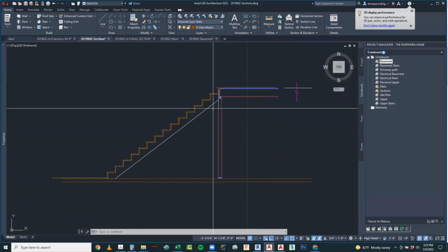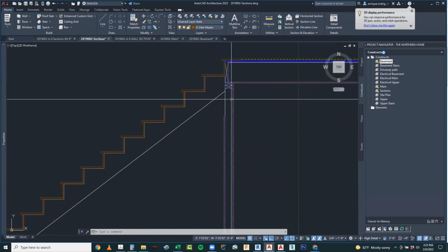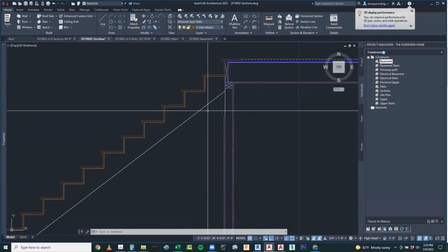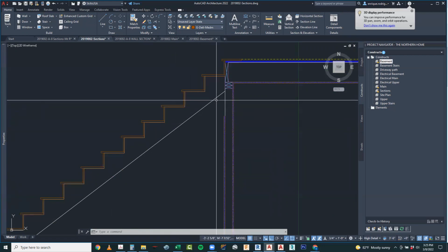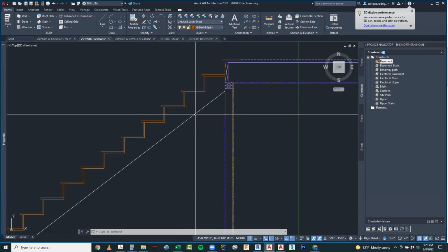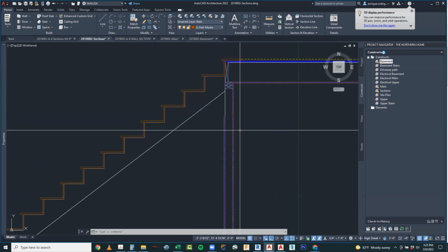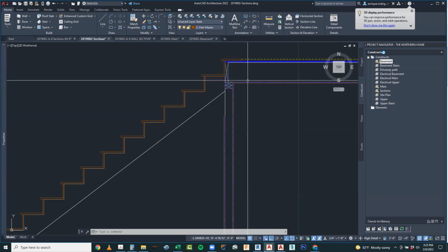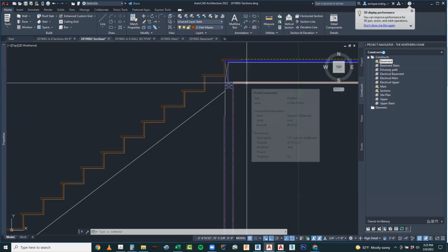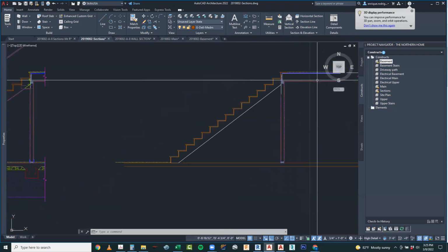And we're going to put what's called a 2x4 nailer right here so that we don't have to bring our drywall to this awkward point right here. So it's going to go up, cut across, and come down. Now that's very important also because you can't get a tool in there to put the final fasteners onto the edge of the drywall up in this corner.